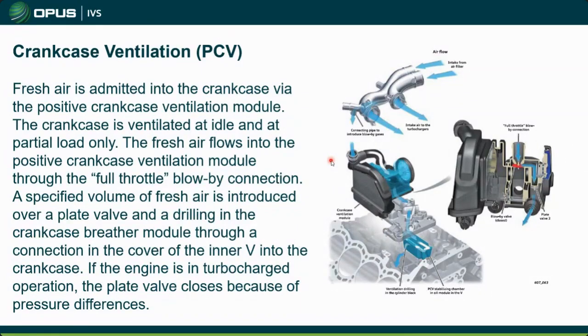It basically shuts off the breather system if you're at full throttle, and that kind of makes sense, because you're pushing a lot of boost with the twin turbos and the V8 and a lot of volume, and how long are you really at wide open throttle? It's not long enough to build up enough gases that this system can't be stopped from venting for a few seconds.